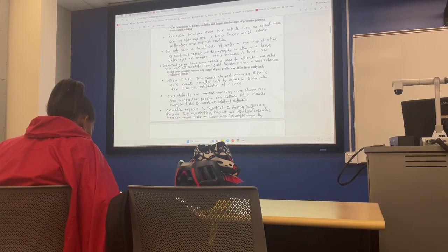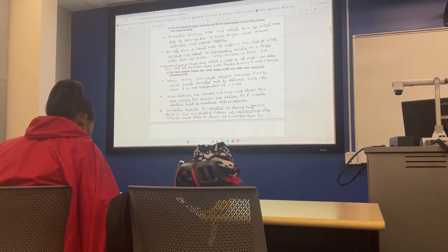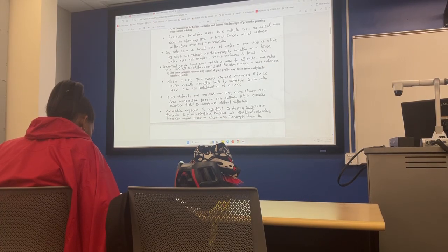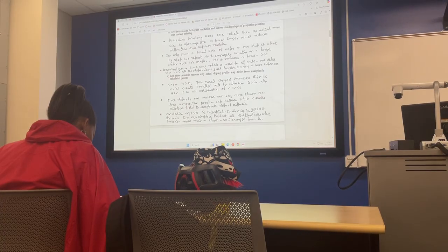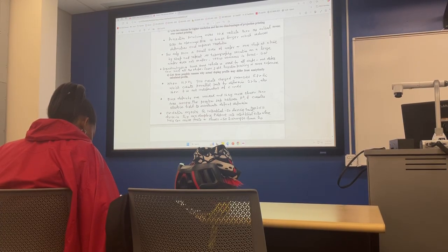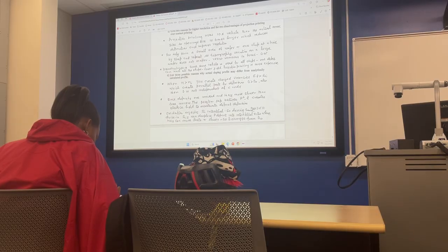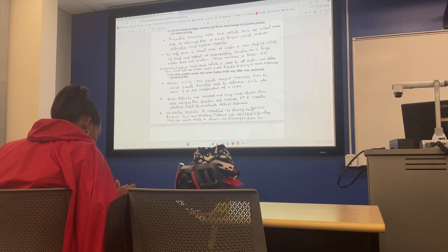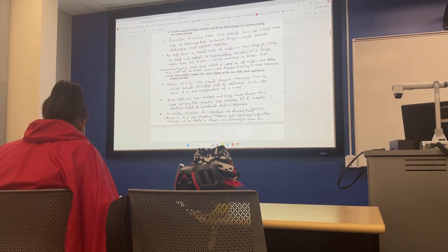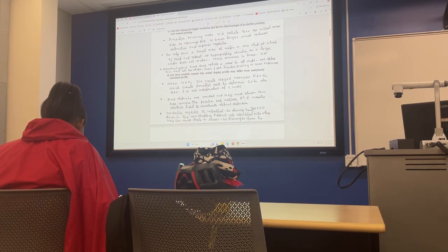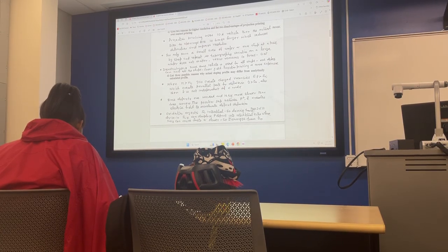So basically, one reason was that D is not independent of the position or the concentration. That's number one. Second, there is a field-assisted diffusion also happening because of the ionization of the dopant. And the third is, if the silicon interstitials are being injected, they knock the dopants out from the substitutional site to interstitial, and that can change the diffusivity, because interstitial diffusion is different from the substitutional.